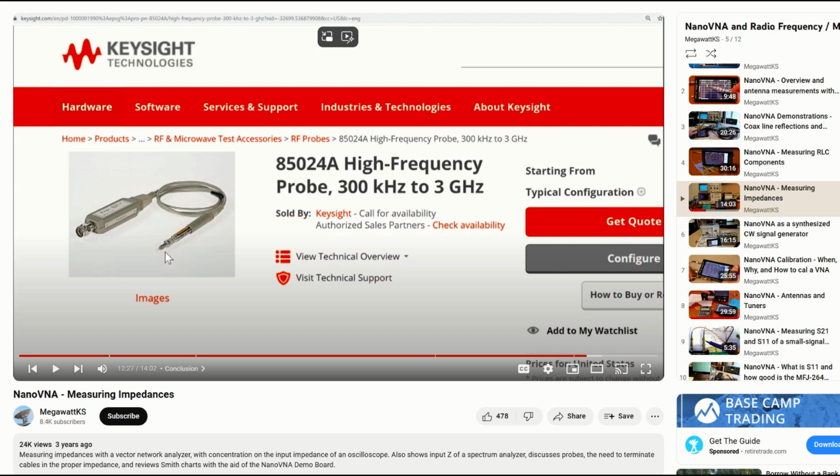The way they get that is they use an amplifier at the tip here that can then drive the 50 ohm cable, or whatever the impedance of the cable is, back to the oscilloscope, or spectrum analyzer, or network analyzer, or whatever you're using this with. The downside is these things are fairly expensive, although I found some on eBay. That's how I got them for the lab.